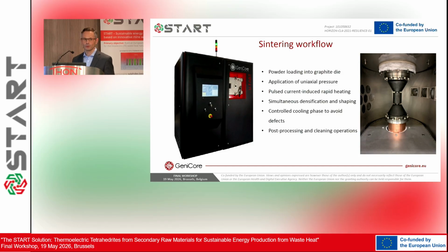Very often we use some low temperature annealing to remove absorbed gases on the surface with the aim of increasing the final density of the material. This stage takes around a few minutes. When we have full operational vacuum in the chamber, we can go further with the heating, and the same at the cooling stage to limit the cracking.